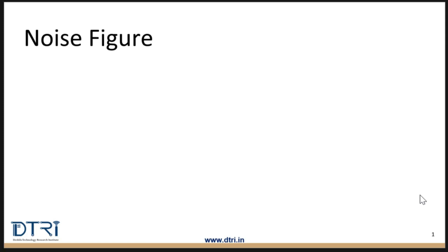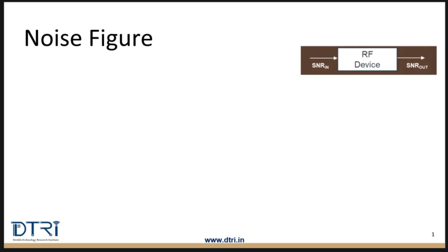As an RF engineer, you may have heard and worked with a key figure of merit, which is noise figure or noise factor during receiver system design and analysis. Noise factor, by definition, deals only with noise powers. So consider this RF device. Let's say this RF device is fed with some noise from a noise source.